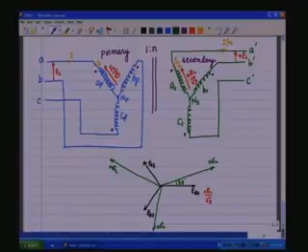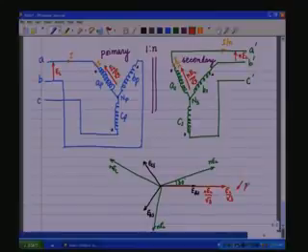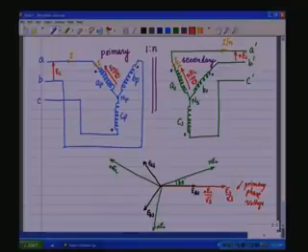Now, the phase voltages of the primary side of the star will be in phase with these, and that will be, let us say, N times, that is EL by root 3. This is the primary phase voltages for one phase, likewise for the other two phases also.